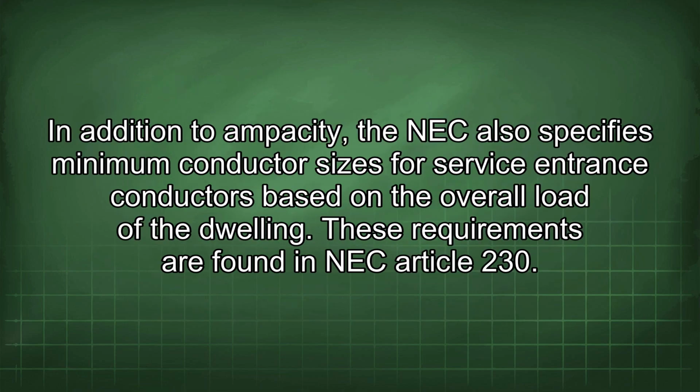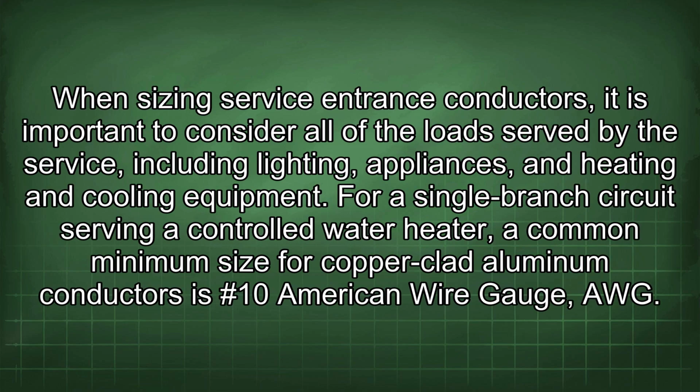In addition to ampacity, the NEC also specifies minimum conductor sizes for service entrance conductors based on the overall load of the dwelling. These requirements are found in NEC Article 230. When sizing service entrance conductors, it is important to consider all of the loads served by the service, including lighting, appliances, and heating and cooling equipment.